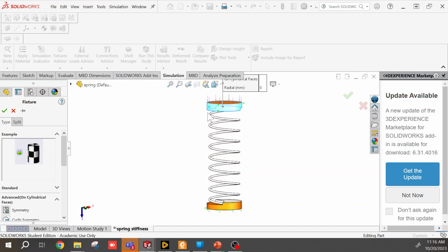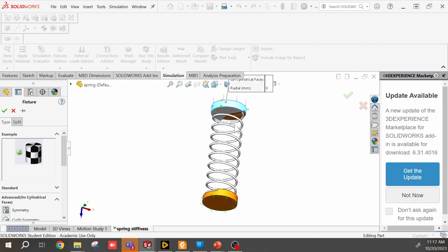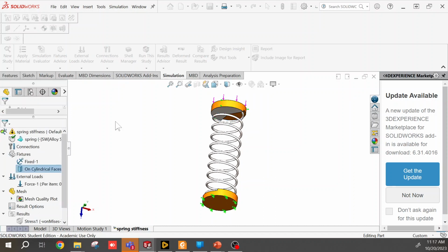You might be very careful when you're pushing down a spring in your life, and you're like, I'm going to be super careful, I'm only going to push vertically. And in this case, the forces are perfectly vertical, and the constraint is perfectly vertical or perpendicular, so it's not a big deal. The problem here is the curvature of the spring and the fact that it's not totally symmetric in where it starts and where it ends. So that's the issue here. That's why it's going to blow out to the side. So I'll show you.